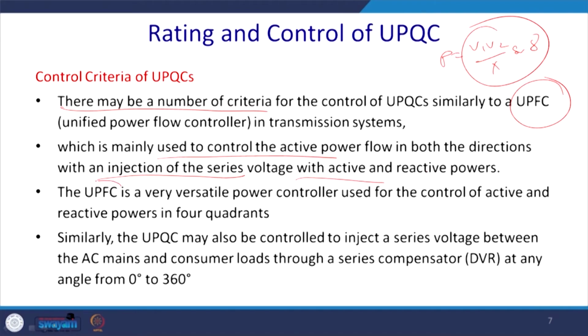Generally, we need to know the features of the UPFC to better understand the UPQC. It is a versatile power flow controller used to control the active and reactive power in all four quadrants. That means power can be positive or negative. Generally, this is I and this is V. So you can operate in any of these quadrants: voltage and current can be positive with respect to the reference, and the current can be in the negative direction.